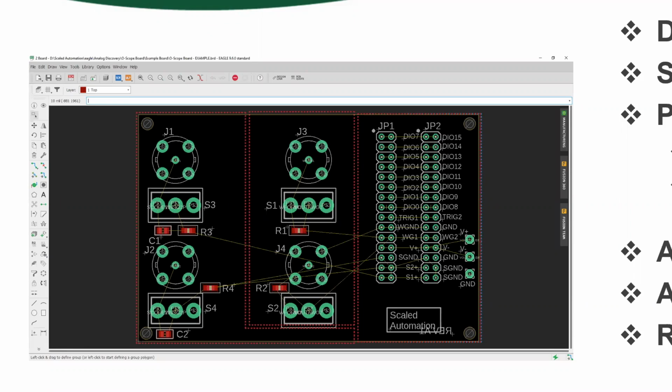So once the components are placed, those are called air wires, by the way. That's the term they use. They're not wires, and they're not in the air, but they're called air wires. But they're used to show you the signals. That shows you where every component connects. And so we're going to turn those air wires into traces. And again, the auto tracer can do that, or you do it manually. And we'll show a few examples of that today.